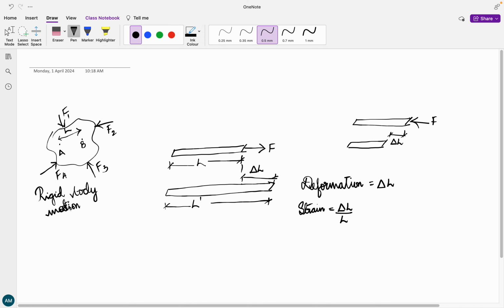If the shape and size of a body are altered, that is, the distance between any 2 points of a given body changes, it gets transformed from one configuration to another, then we say that a deformation has occurred. The matter present in the neighborhood of each point is translated and rotated and thus strained.